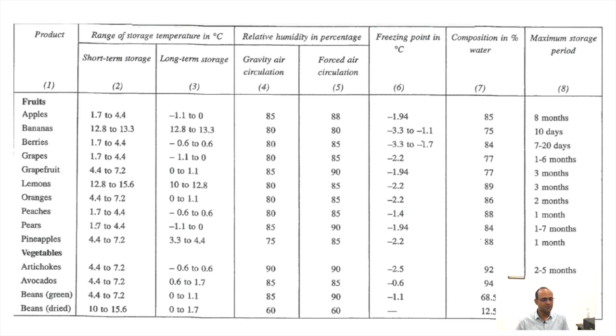Now here one thing is very important: with higher temperatures, normally the relative humidity value decreases, and if that decreases, it will start taking the moisture from the product. So there will be a moisture loss during the storage, and therefore a good combination of relative humidity and temperature is a must for ensuring the quality and that moisture loss is minimum.